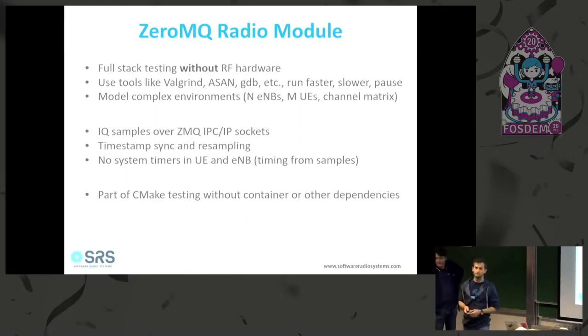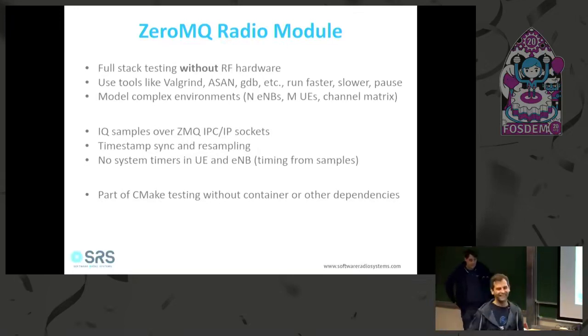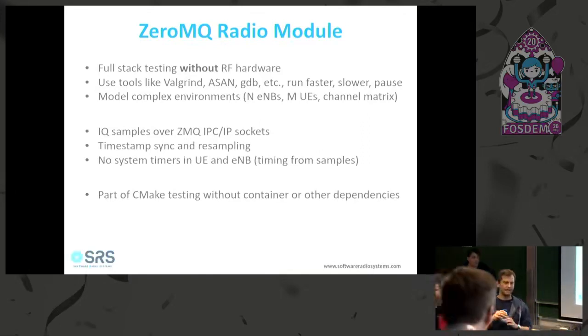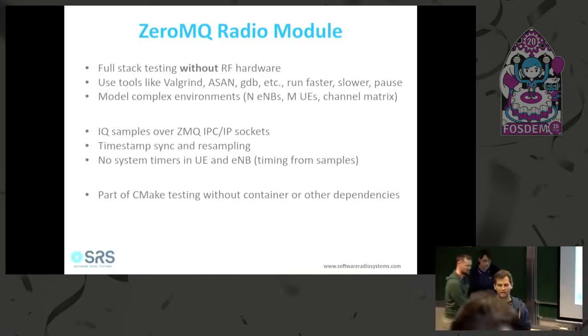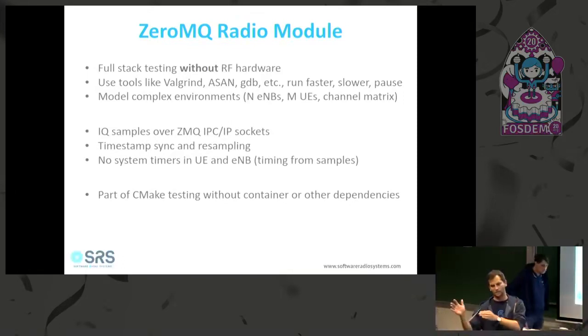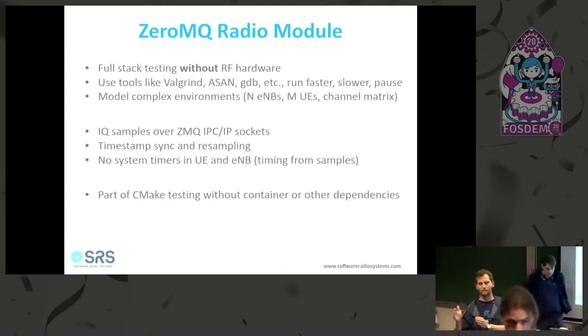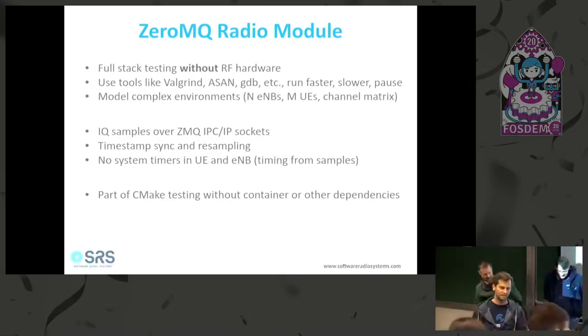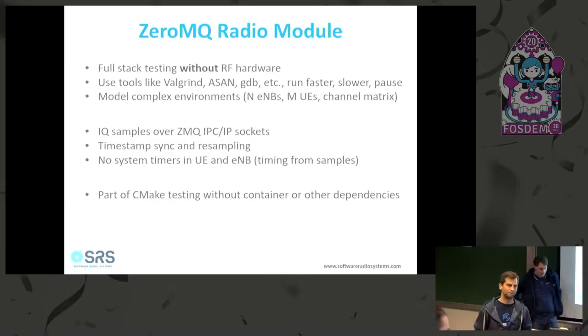Have you looked at implementing that on the Pluto? Thanks for that question. Yes, the question was if we have been looking at the Pluto to implement LTE. Two things. LTE really requires strict timing. We need to know when we receive samples what the timestamp is, and when we transmit them, because the transmit is always aligned to the receive side. What we need to add there is timestamp support, because the Pluto libIIO doesn't have timestamp support. That's something we're adding this year.